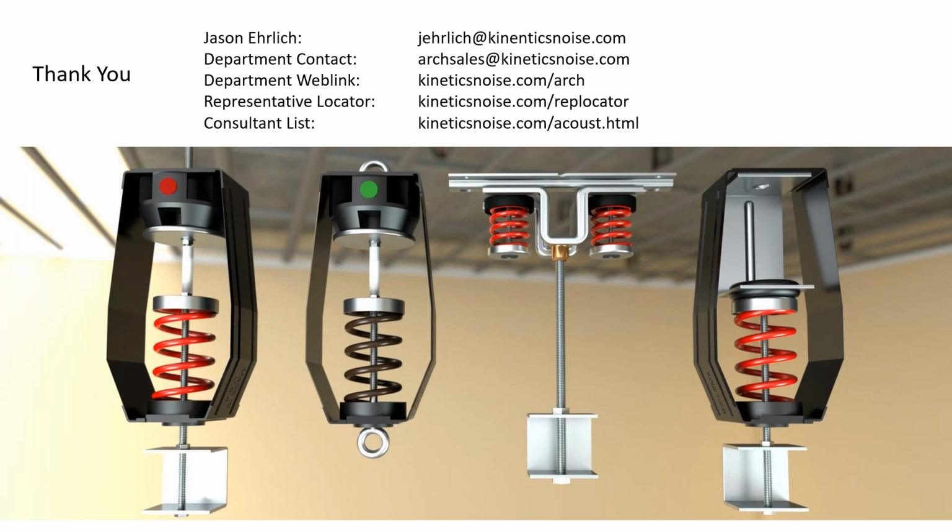Obviously the big challenge with these things, especially on those quote unquote kitchen sinks where you've got ducts and pipes and everything else, is that coordination aspect. There is some flexibility in our layout, but generally what happens is that ceiling grid itself is the constraint on how much weight it can take, and we have to sometimes tighten up the ceiling hangers just so we don't overload the grid. Hope that answers your question.